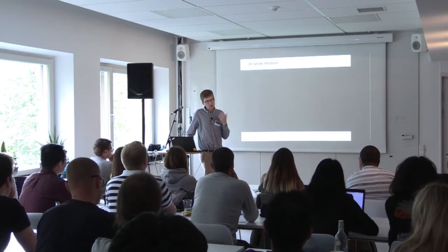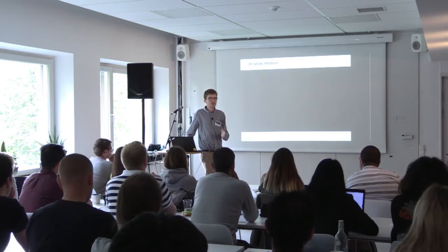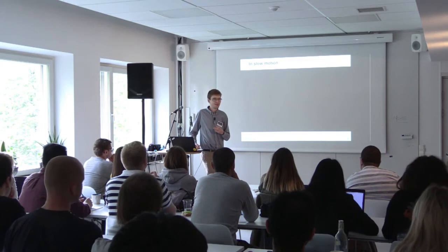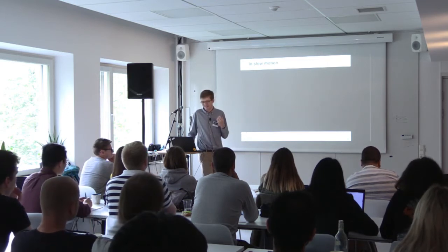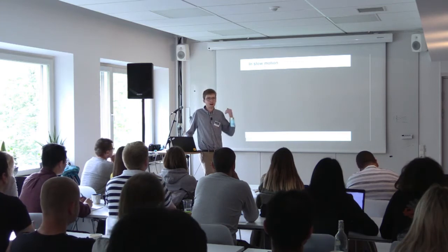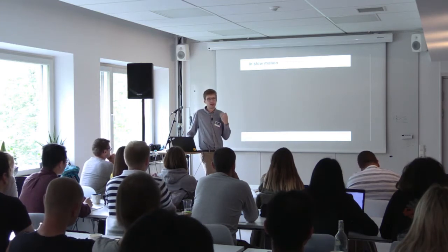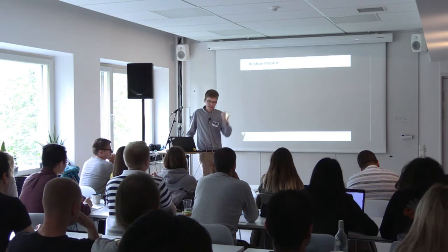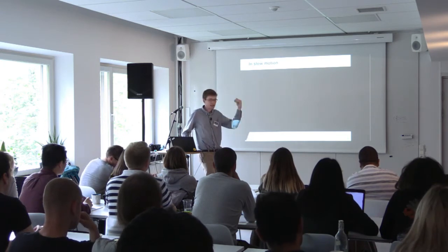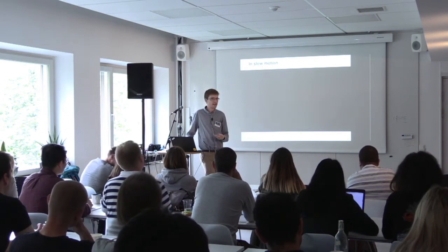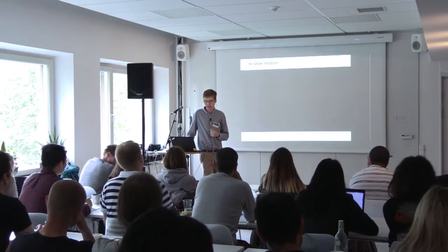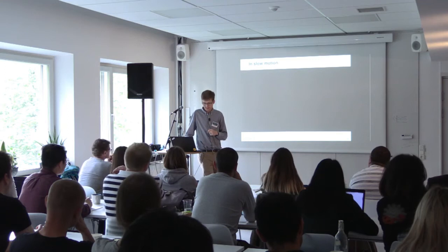Of course, this will not be useful if you're trying to, say, take photographs of people's houses and you lose one of your propellers. Your photos are going to be mighty blurry. But at least in the safety sense, you can now bring this vehicle back home safely, right? And you have the ability to bleed off the potential energy that you had when you were hovering high and bring the vehicle to a soft landing, even if you can't control the orientation, the yaw angle.